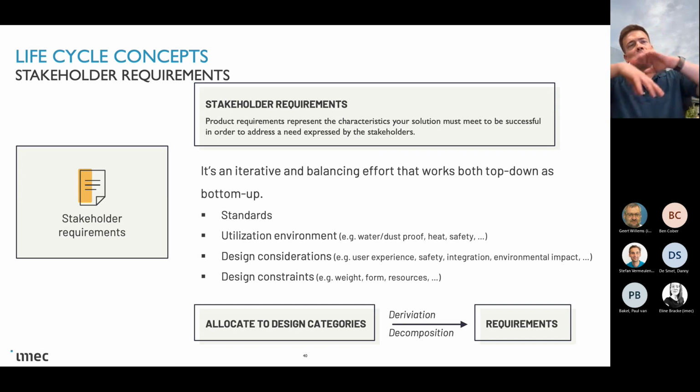Sometimes you have, let's say, a handheld device, so that, of course, is a top-down way that you have a dimension constraint. So of course this trickles down all the way to your PCB sizes, etc. There's also other things. If your sensor is only able to work with this performance, this has of course effects upper on the higher level components as well, and also on your functionality. So both of these things of course balance each other.